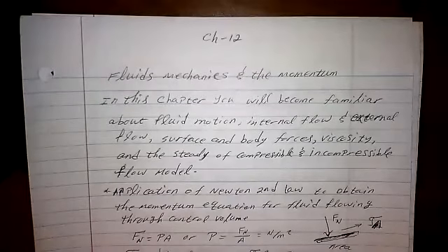Because if you have the air velocity, then you have the change in pressure, because at the point of the pitot tube there is a point we call the stagnation point, where the pressure is higher, but the flow comes to rest. When the flow comes to rest, we call that point a stagnation point.